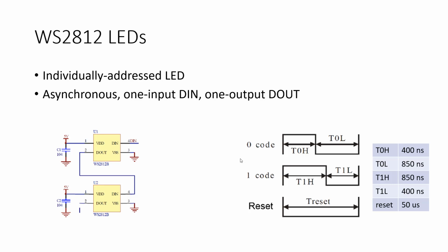When the NeoPixels came out, the idea was that you could get a string of them of arbitrary length, and then you could control individual pixels. And each of the pixels, and when I say pixel, I mean LED, had 16 million colors, which seems like a lot for an LED. But what was really happening was that those were not single LEDs, they were 3 LEDs, red, green, and blue together. And you were individually controlling the brightness, probably through pulse width modulation.